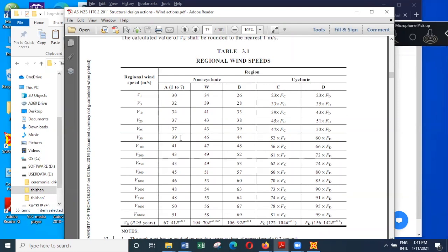So basically, even in Eurocode, the basic wind forces are multiplied by 1.5. So we get load combinations like 1.35 dead load plus 1.5 times wind load. So the net effect is, when you use the partial factor of safety, you use the service wind and multiply it by the partial factor of safety.